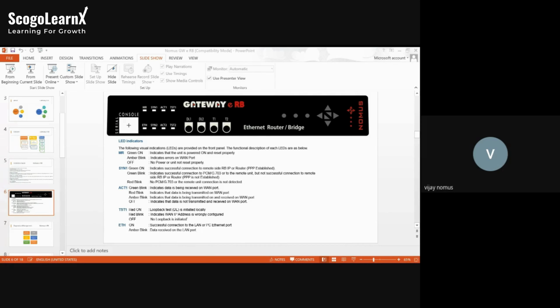So for resolving that, we need to remove the local lead from the MLLN device and non-MLLN device. The BSNL local lead, you have to remove it. After removing it, if the amber LED is still blinking, then we can confirm the errors are coming from the V35 interface. We have to raise a complaint to the BSNL. The errors are coming from your MLLN modem,